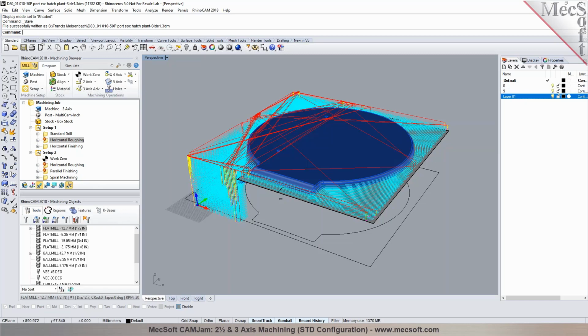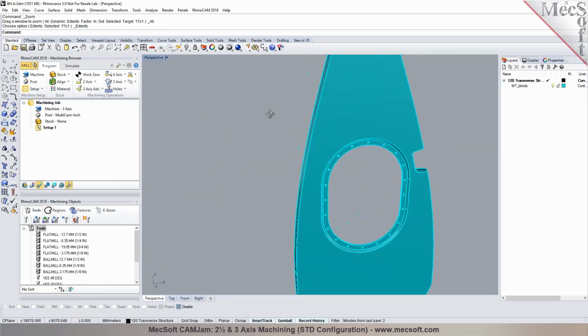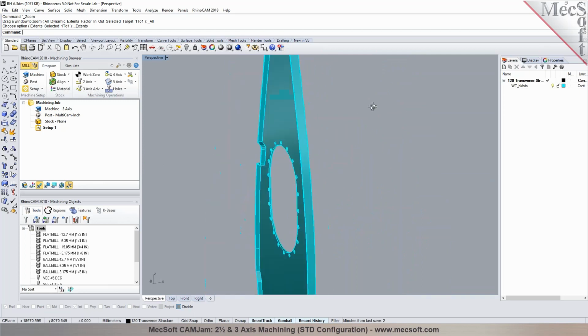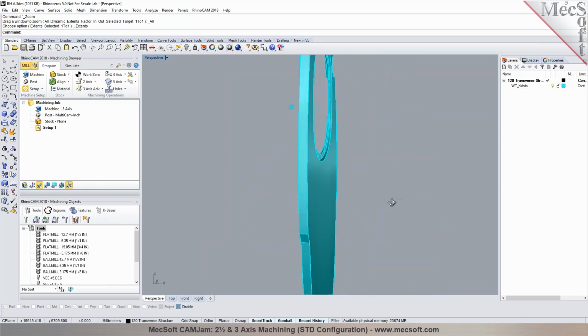And then you can modify the library and make changes as needed. Okay, awesome. It doesn't automatically set these to a tool number. Yeah, the tool numbers aren't defined in the library. You would have to set them because it could be different for each tool. Usually user defined. So, this part looks more like a prismatic part, right? Exactly. Where there are many drafts, you can do 2.5D operations.